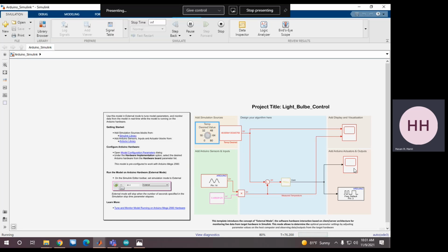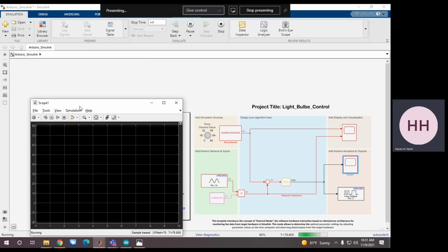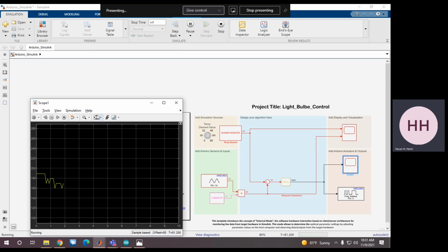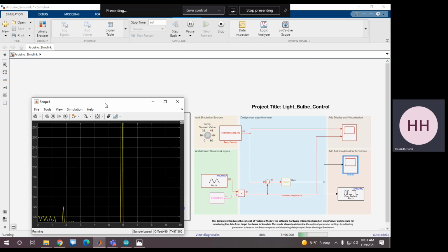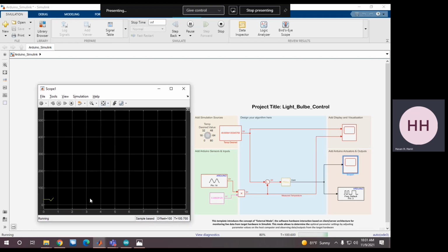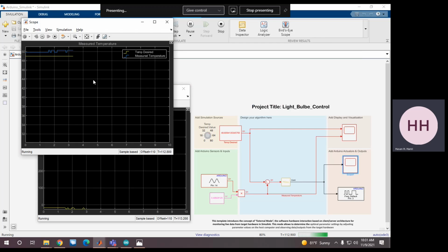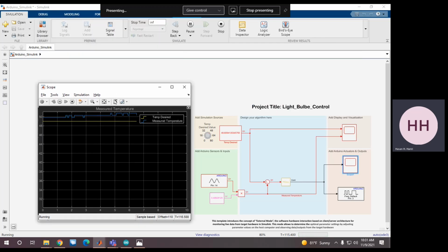And this block is the PID signal the microcontroller is generating. It's a PWM signal, but you can't see it as PWM. It's just decreasing, coming closer to 0. Now the lamp is off, and as you can see here, I have reached my temperature.